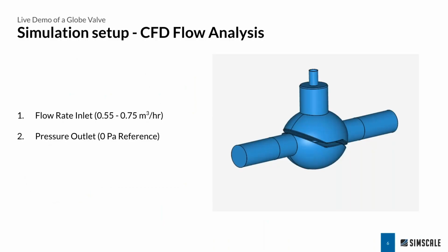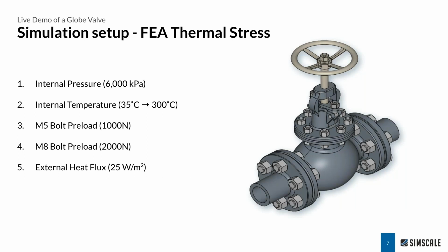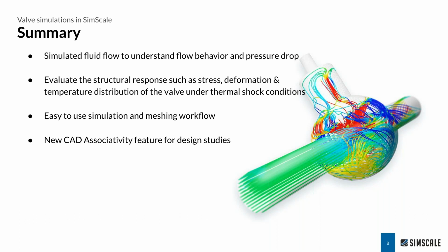So here were the operating conditions of the CFD flow analysis. We've iterated between several different flow rates in the inlet and a reference pressure in the outlet. For the structural analysis, we've simulated the internal pressure from the thermal shock, the internal temperature from that thermal shock loading condition, and the bolt preloads, as well as the heat flux, modeling that convective heat flux leaving the system. So in summary, working with the SimScale platform allows you to look at,